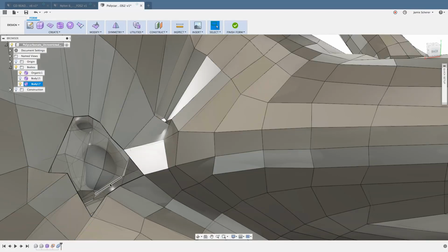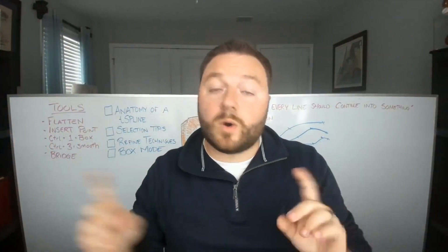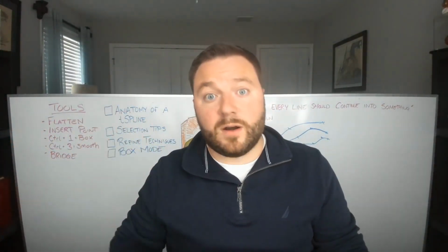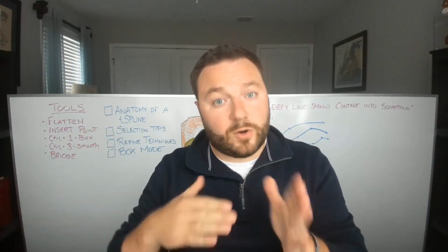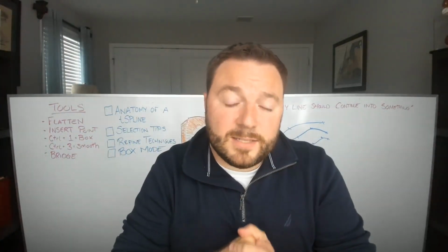The other thing that'll come in handy, if you have a scenario where maybe you have 2 faces on one side and 3 on the other: Bridge is always going to want to make you transition from the exact same faces on one side to the other, or multiples of one another. So 2 faces can bridge into 4, 3 can bridge into 6. It'll create T vertices, or a T intersection in those instances.